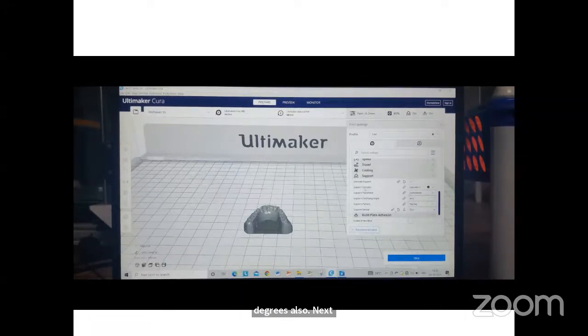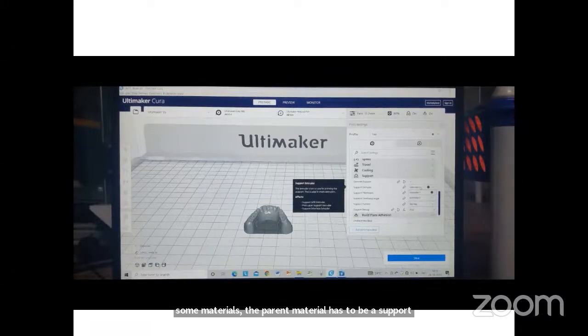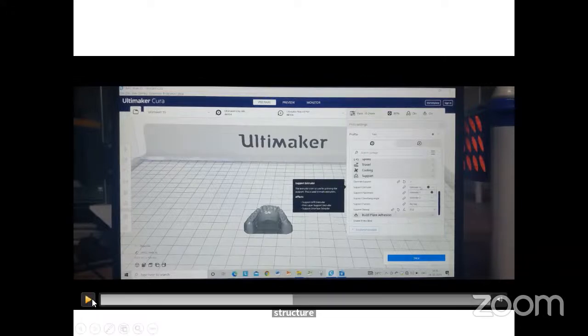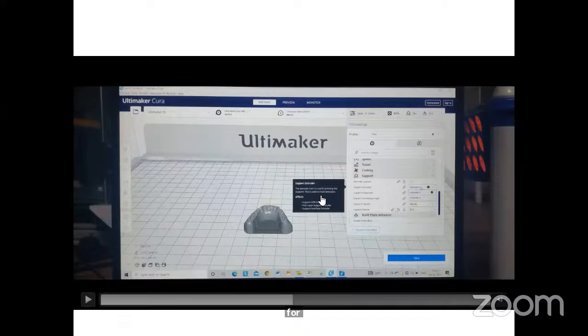Next thing is the support extruder. For some materials, the parent material has to be a support. But for PLA, you can also go for Ultimaker Cura software, download freely. It's available online and you can practice a lot. You can take some STL file and put layer thickness, change everything, how the build time and material are changing, and also you can investigate by changing the hatch pattern or the layer thickness or build orientation. All these things you can study without having a 3D printer. You can study with Ultimaker.